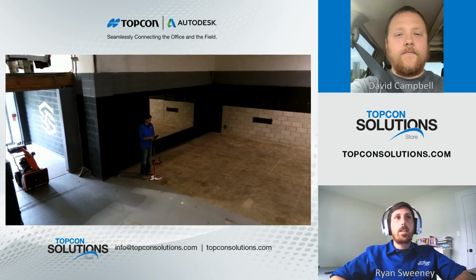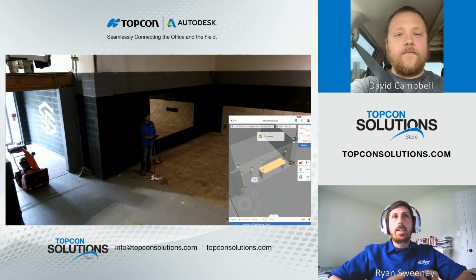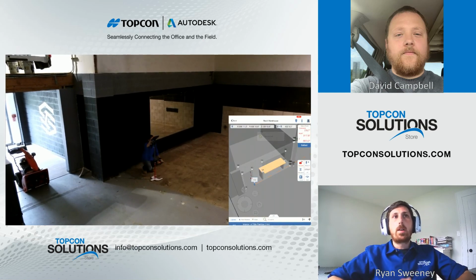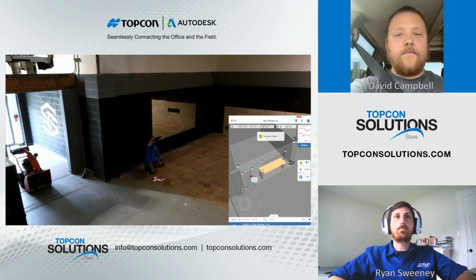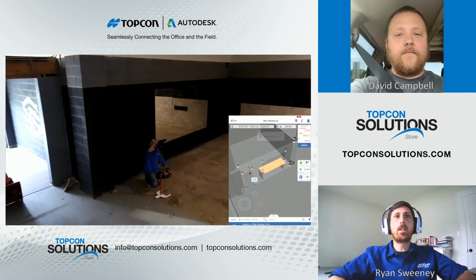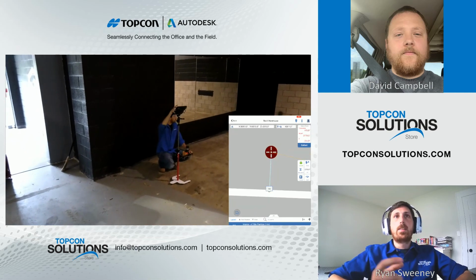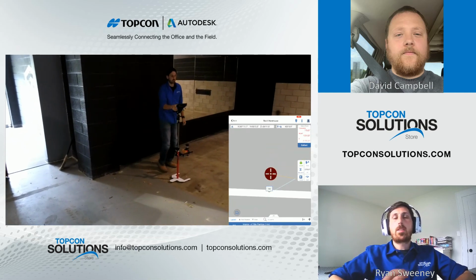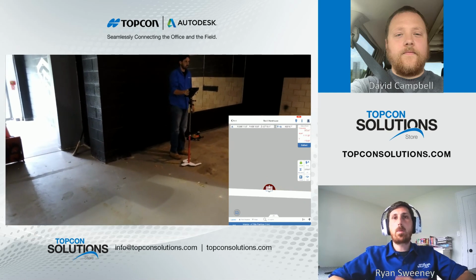Okay, so you'll see here, we're starting to lay out our points. I walked on right on over, and now you'll start to see the fine movements. The total station will track you as you move, and it'll direct you right towards the point on your iPad screen. So you can see that here as I'm adjusting the XY positioner and that laser light. You can see in the upper right hand corner of that iPad screen, those numbers and that distance to the point get smaller. So once you land on top of that point, you're good to go.